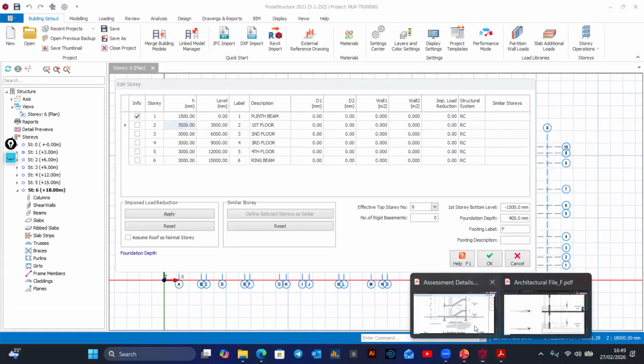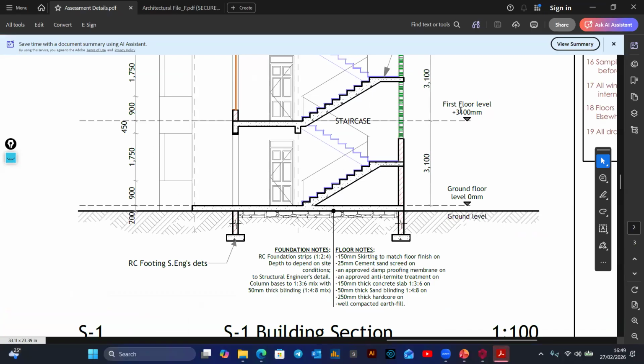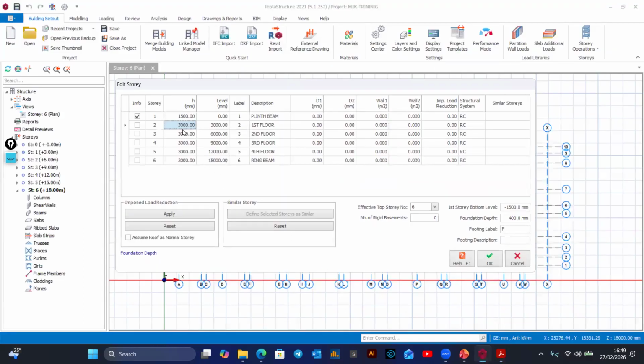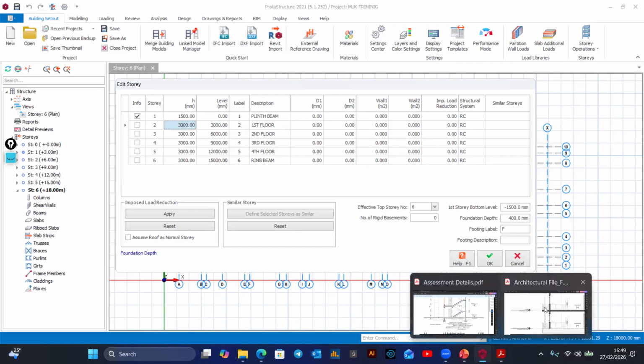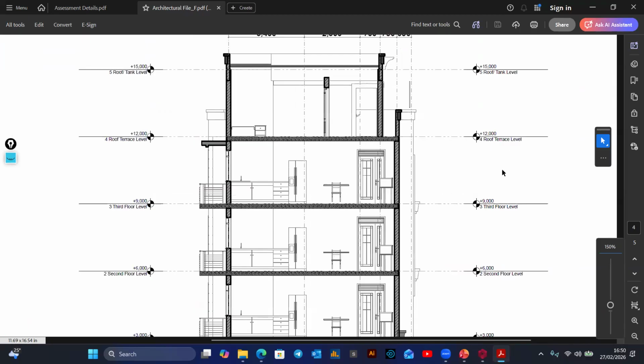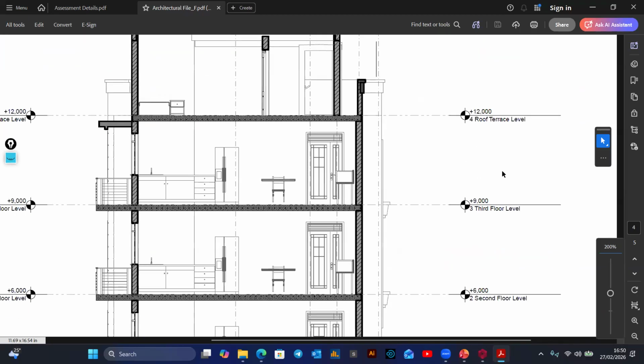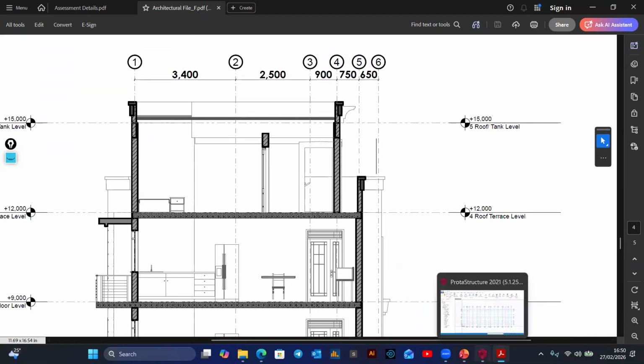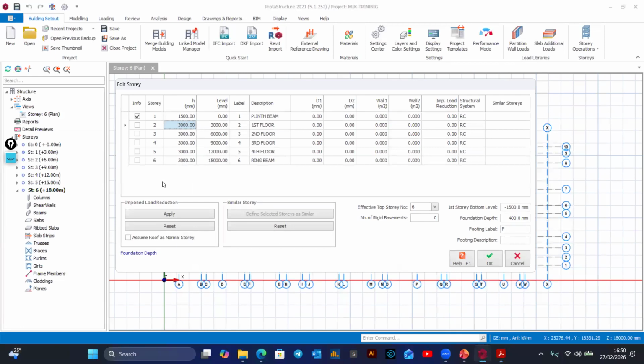I don't know for this other file that I shared with you, this is now 3.1. So even in your design, I would expect you to have 3.1 here, like that. So the headroom here, the height h, is this distance which you get from the section, from this cross section. Floor to floor height. So here is 3,000 all through. I'll just keep it like that.